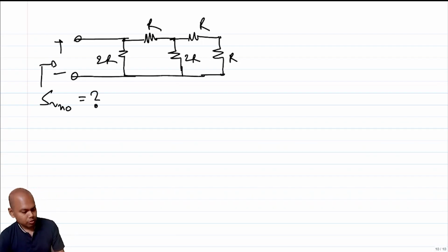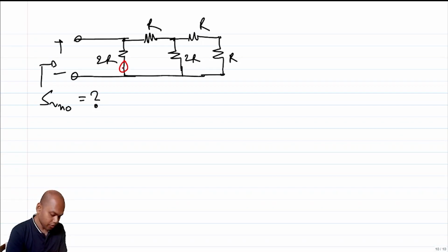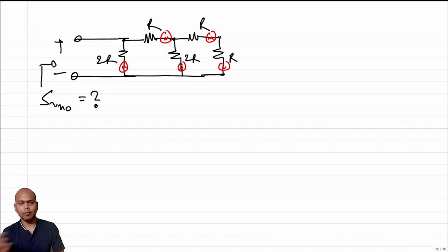So if I had to stick by the old process, what did I have to do? I had to find out the transfer functions from each of these resistors to the output and then sum them up and multiply them by 4kTR. Since I have 5 resistors, or maybe I can simplify it to 4 resistors, I have to find 4 different transfer functions. But I don't need to do that now. All I need to find out is the equivalent impedance, and in this case there is no imaginary part, so 4kT times the equivalent impedance.